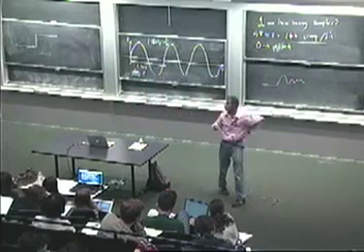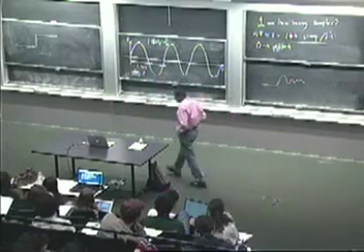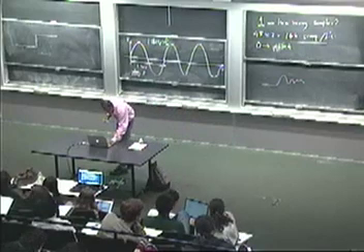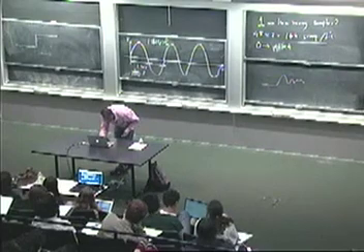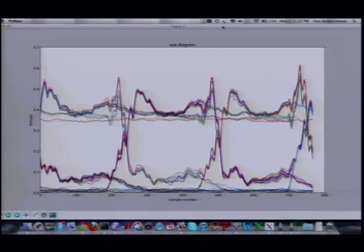So the eye diagram is a way to capture that. What the eye diagram does is it's a kind of clever hack. I thought I had it somewhere. There it is. The way you generate an eye diagram, you don't have to worry about writing the software for it, but you will look at a lot of these kinds of pictures in Lab 5. You transmit a random sequence of bits. And then you look at the samples that were received at the receiver after the demodulation was done.